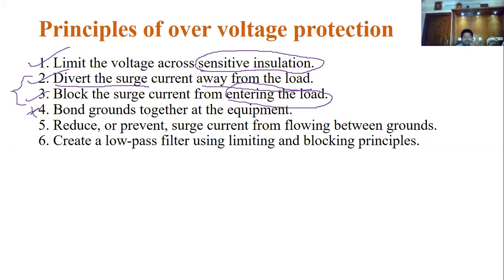Now this is an important characteristic: bond grounds together at the equipment. I will tell you in the coming slides what this bonding of grounds is to protect the equipment. This reduces the surge current flowing between the grounds.